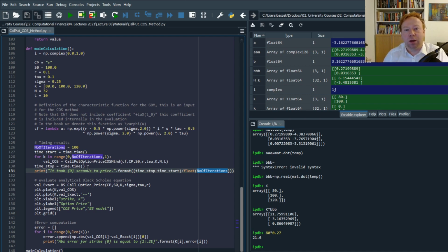A number of variables could be initialized, which is rather expensive, and the second or third run could already have them available. There could also be a slowdown of the system. So for that reason, especially if the simulation takes very little time, it is very advisable to repeat the experiment many times and then take the average of the time needed for all of them. This is what we do here.